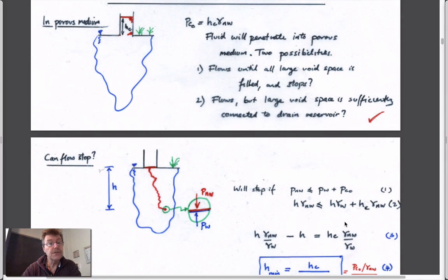So what we could do is try applying that not to the case where you have two fluids on their own, but two fluids with porous media. The case for that would be if you now take a porous medium which you saturate to the surface with water, and you take a 55-gallon drum on the surface, and you put something in it such as a NAPL. And now if you do that, then you look at the pressure that that column of water would apply right at the surface of this, and you can do the same calculation.